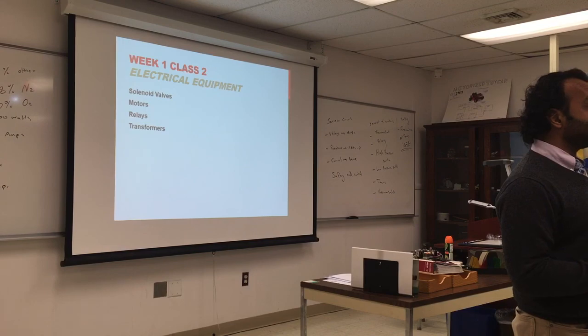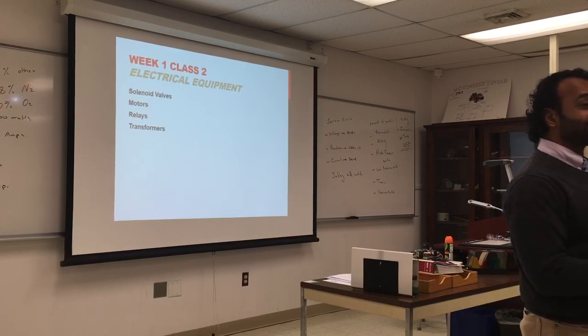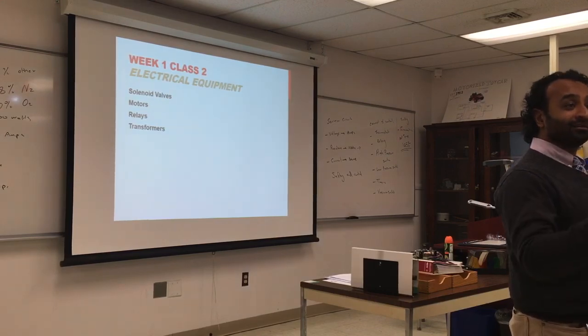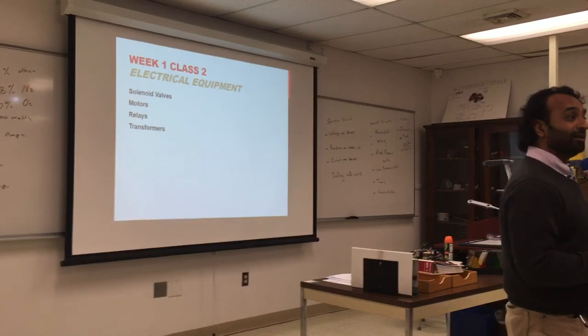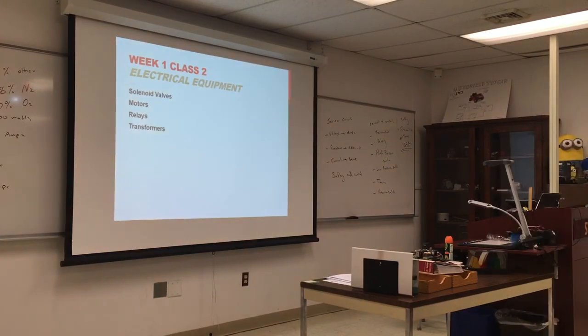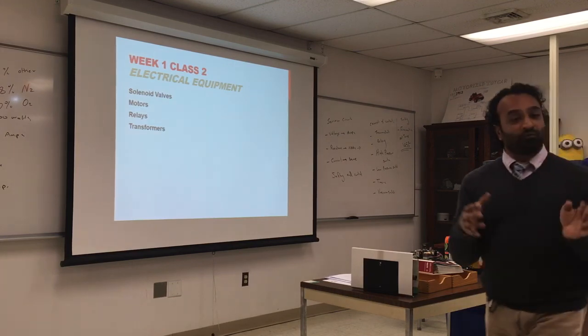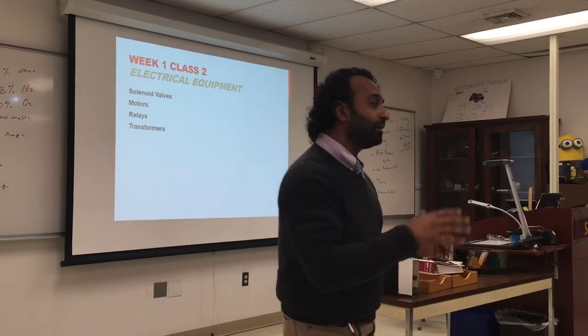Power. Horsepower. And what else? RPM. What else? What's the frame? Torque, horsepower, what else? Single phase. What kind of power does it take? And what else? Think about the hertz too. There are so many characteristics, but for us, we have to match the RPM.